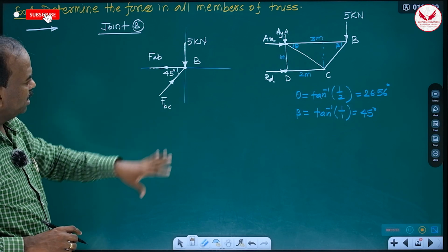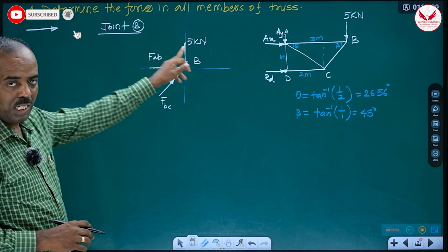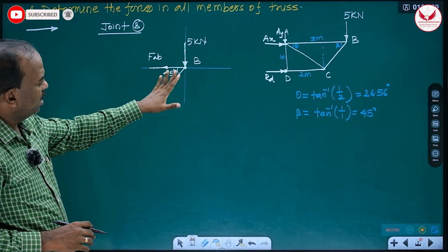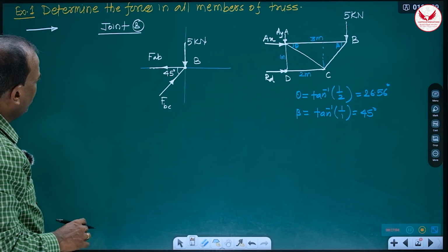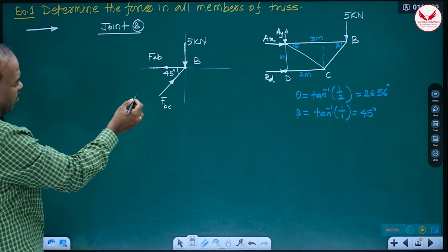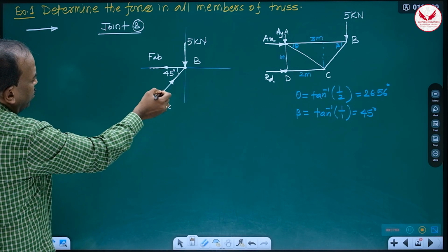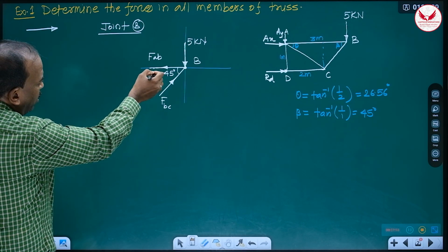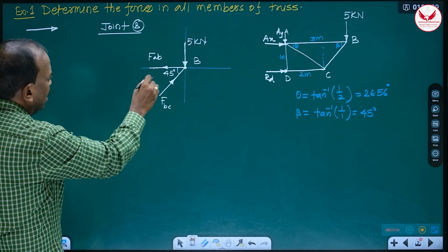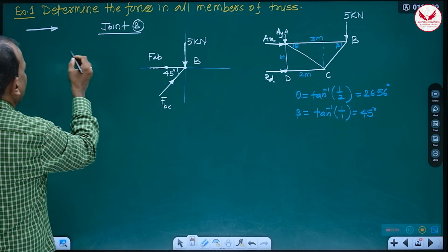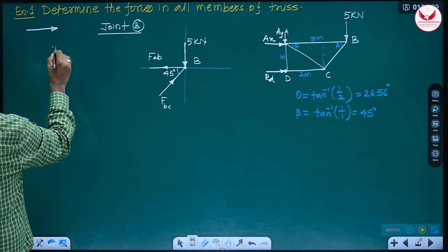So for solving this, even though three forces are acting at a point, they are not all in one direction, either away or towards. So do not use Lami's theorem. Simply use the basic conditions of equilibrium. There also, which condition should we use first? When the unknown is horizontal, use summation Fy first. When the unknown is vertical, use summation Fx first. Here the unknown is horizontal. Then the first condition will be what?